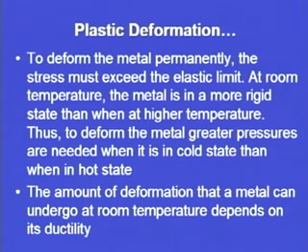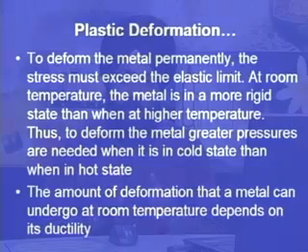If a metal is ductile, it can undergo a certain amount of plastic deformation. If a metal is not ductile, if it is brittle, then it will not undergo that much deformation, and it may deform slightly and after that have a brittle fracture. So, how much deformation is going to take place depends upon the property of ductility.